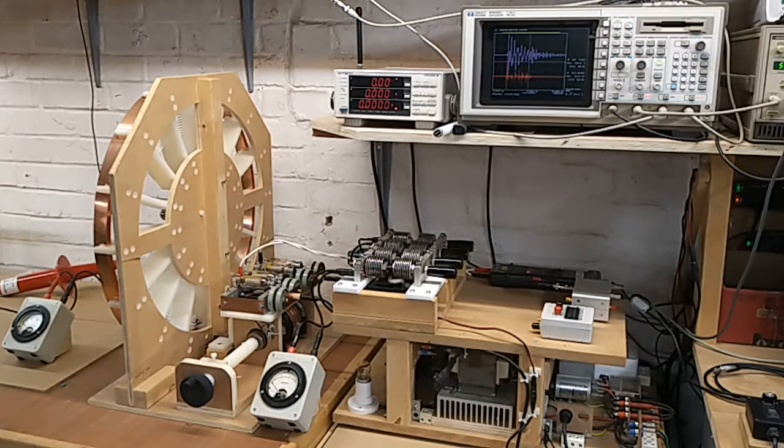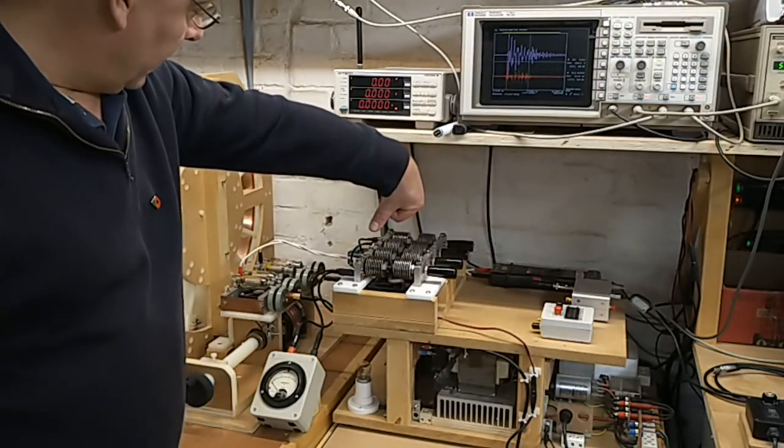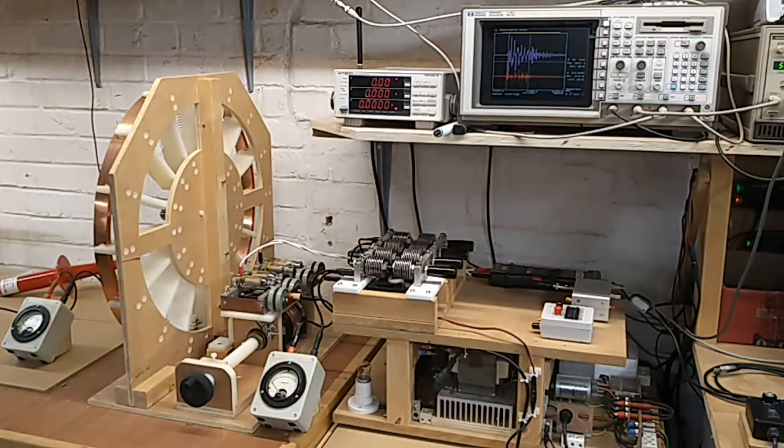What we're going to do is just have a look at again how Z11, the small signal AC impedance of the circuit, looks from the spark gaps through the system. So in other words, what the impedance of the circuit looks like from the generator's perspective. And that will be obviously from the points of the spark gap, so from here. So how does the circuit look looking this way from this point forwards into the circuit?